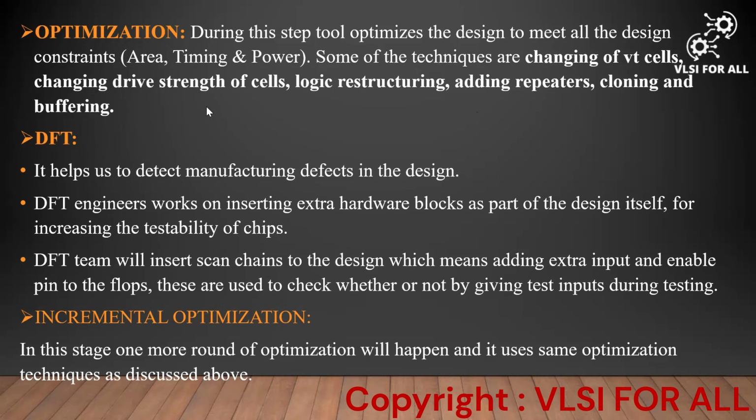So all these steps will be performed in the optimization to get a better optimized netlist, to meet the design constraints. In our VLSI design, the constraints we mainly focus on are three things: one is area, another one is timing, another one is power. In order to meet all these three constraints, these are the techniques which we apply in the optimization stage.